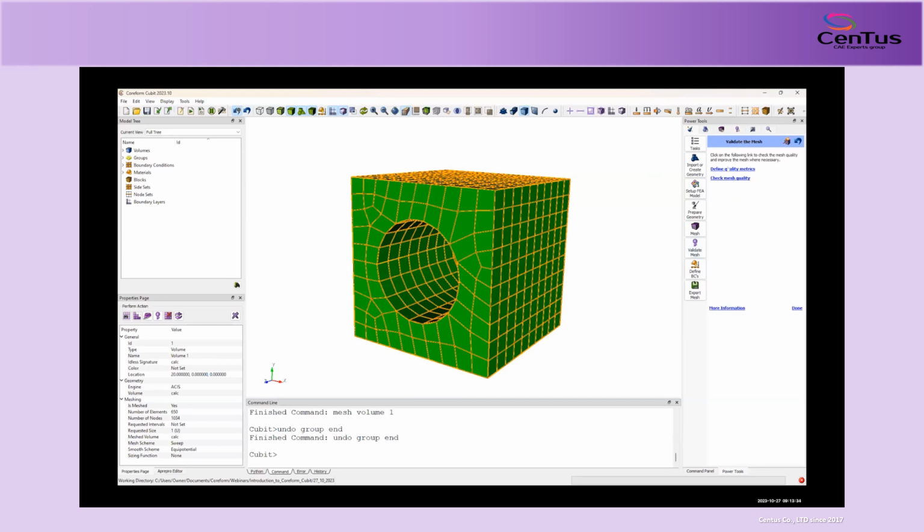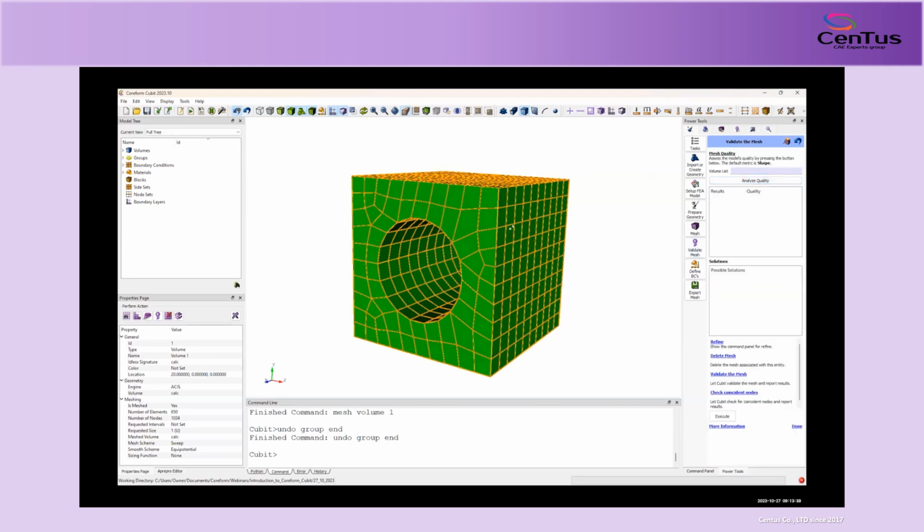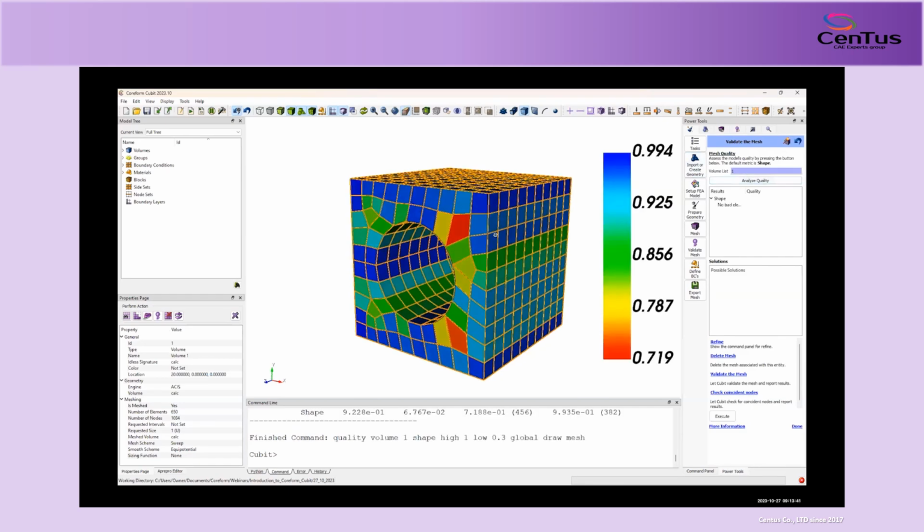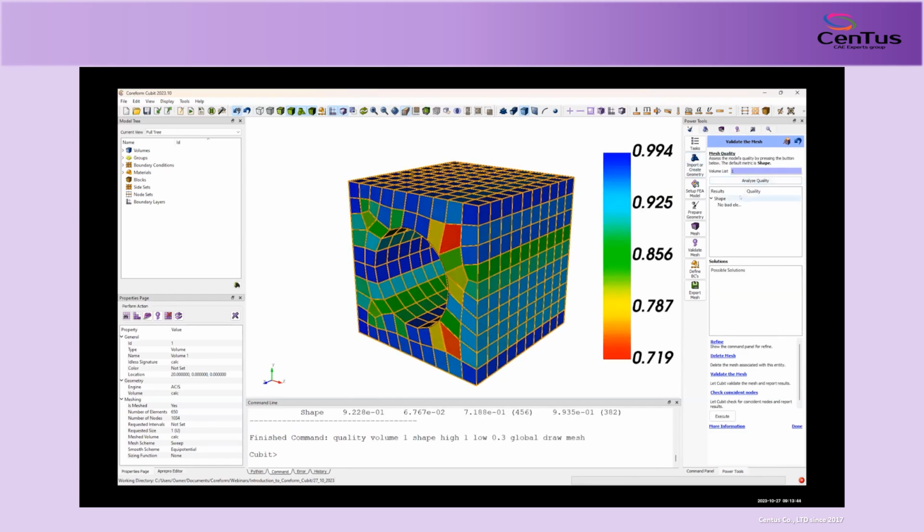You can then do things like checking your mesh quality. For this model here, we're getting a shape quality, and it's telling us that there are no bad entities based on some properties we requested. You can define what those quality metrics are by going to the first step of that, and maybe you want to compare by scale Jacobian, and what your min and max scale Jacobians might be, and you can use that then to check your quality.